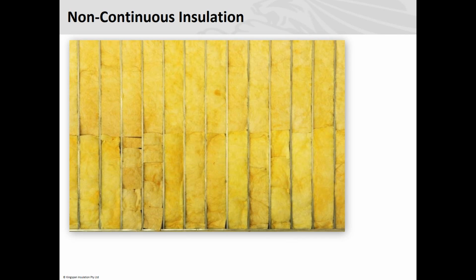Once they heat up to 70 degrees, because this environment's 70 degrees, you're going to come home from work or later on in the day, you're going to have basically 70 degrees sitting up here. So what we say to a lot of the designers is put the air cell insul break under the iron roof, let it sort of dish in between the purlins by around about 40 millimetres to get that bit of air cavity in there, and you can literally reduce 20 degrees off this ambient temperature.